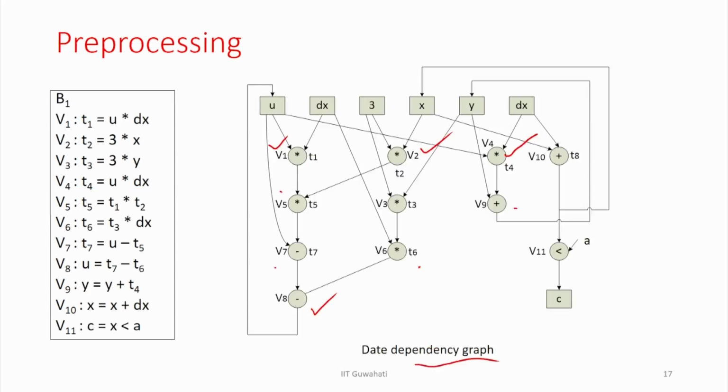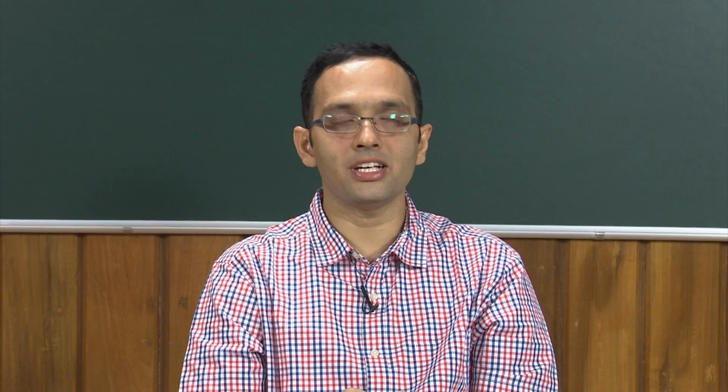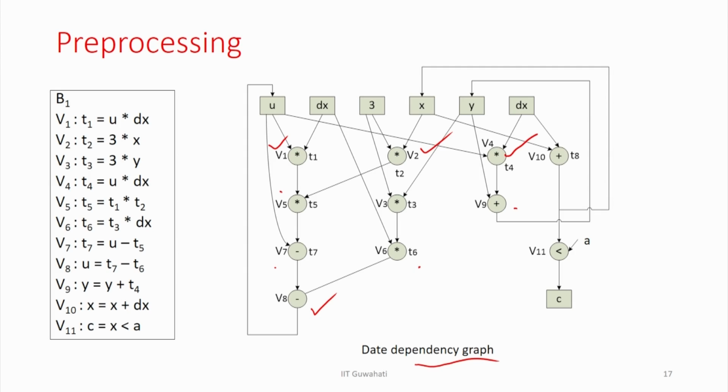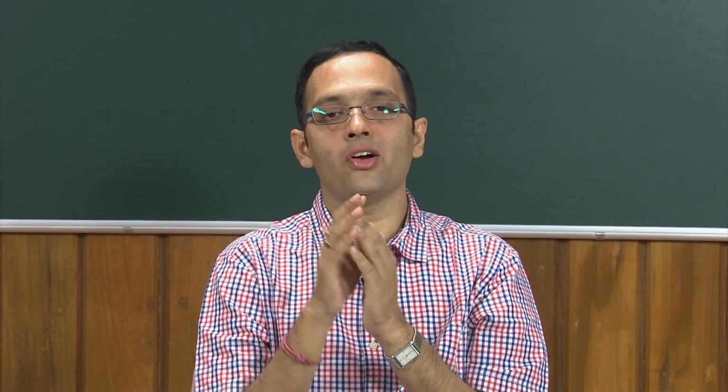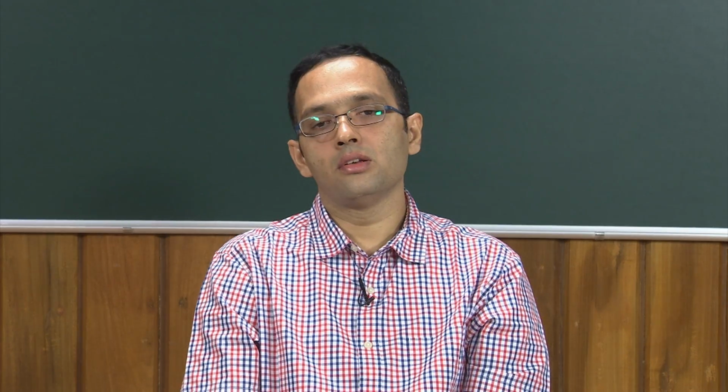So far we have done that. We have extracted this data dependency graph. We can represent the whole behavior as a CDFG, and each expression is converted into three address code. So, this part we have done, right. Now what is the next step? So, this much we understand. Now we have an intermediate representation which is basically a CDFG, where each operation is a three address operation, and we also have the data dependency information. So, what is the next step? The next step is to decide in which clock I am going to execute which operation, right. So, that is our next step.